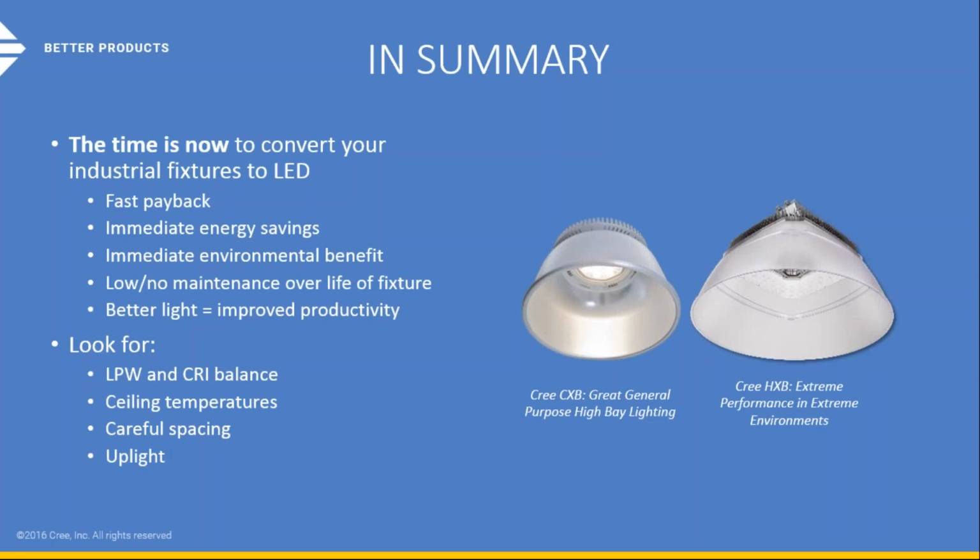Also look at the details. Look at the lumens per watt. Notice the fact that you might be dealing with products that are not equivalent to the color rendering that's required for your particular operation. Also consider the space. Are you in an open space, or are you in a very tight space where vertical light is required? You have flexibility with LEDs that you don't typically have with incumbent technologies to produce the light where you need it. And lastly, being able to generate and utilize uplight with LEDs is one of the critical factors, again, using special reflectors to give that sense of broadness or openness within your ceiling.